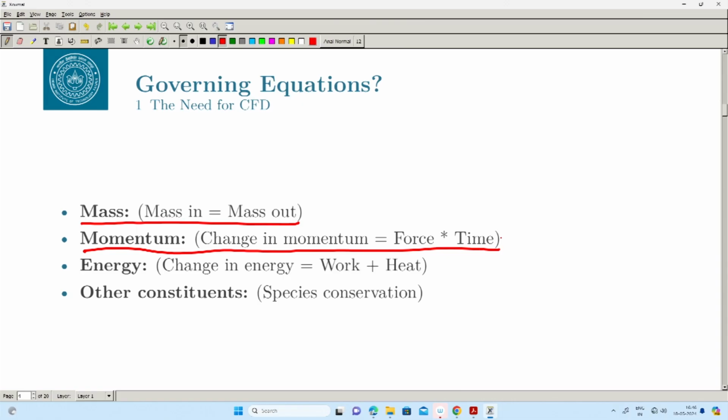So, that is why the control volume approach is more popular in fluids, rather than the control mass approach. In that particular domain you have to ensure that whatever the mass is coming in, the same mass should go out, and if there is a change in the momentum in the system, then it is due to certain force, and it should balance out.